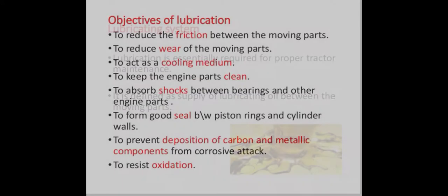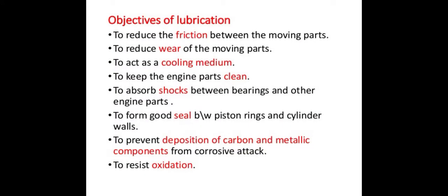Objectives. Its objectives are to reduce friction, reduce wear, act as a cooling medium, keep engine parts clean, absorb shocks, form a good seal between piston rings and walls, prevent deposition of carbon and metallic components, and resist oxidation.